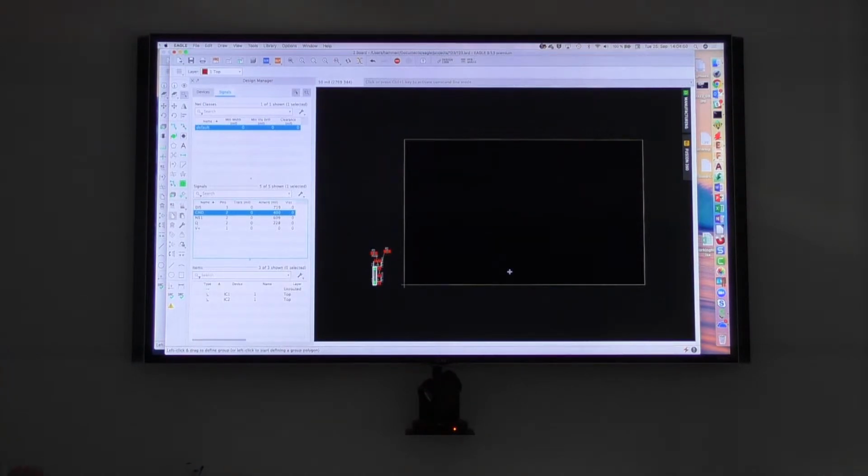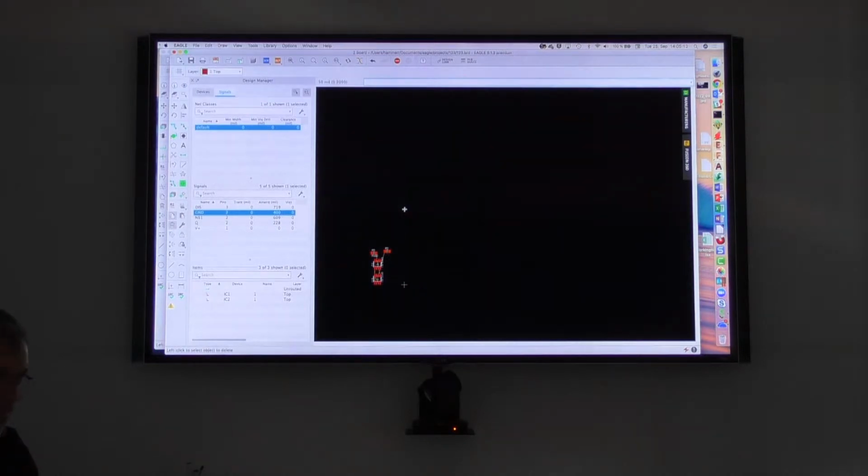Okay, then the next thing is about the board contour. You always get this. If you don't want to have it, you can simply go there, do a group, use the delete command here, and do a control right click, and it's done. It's gone. Now you can draw it by yourself. You could import it from Fusion if somebody has drawn something in Fusion, or I could import a DXF file or something like this if somebody has it, or you draw it. I will make it easy.